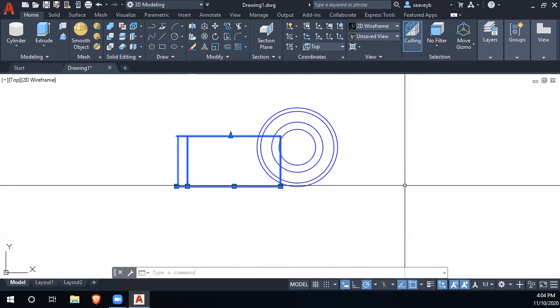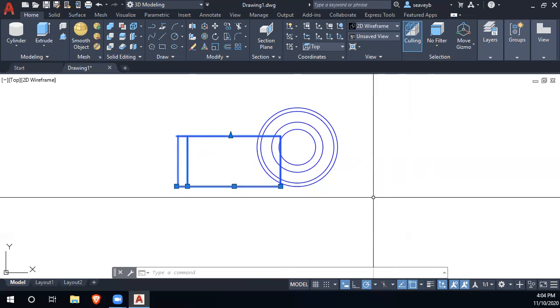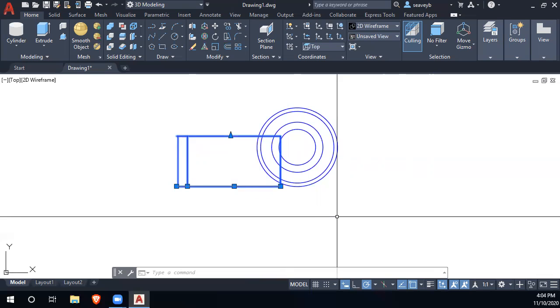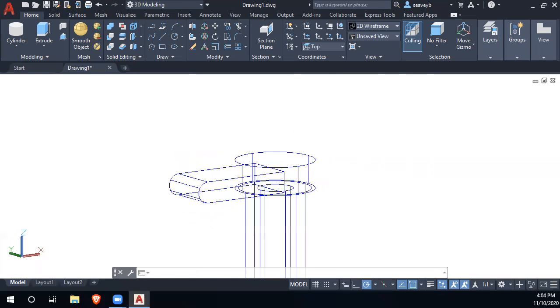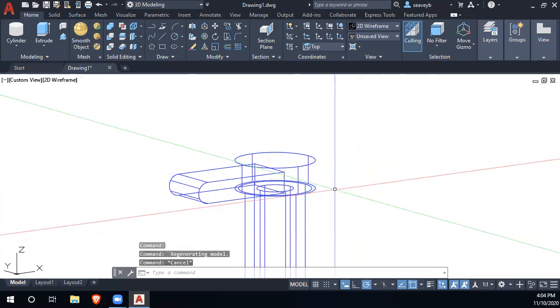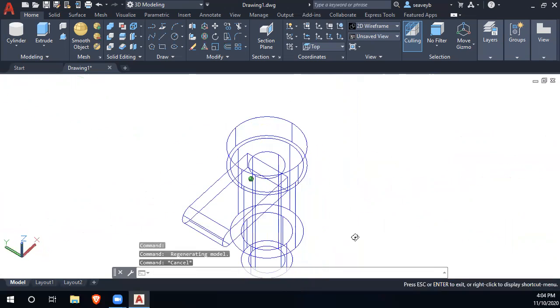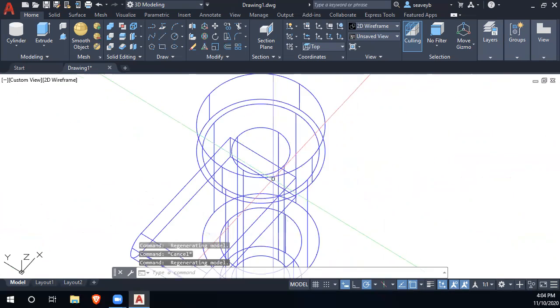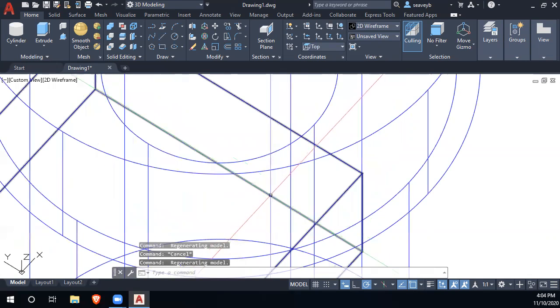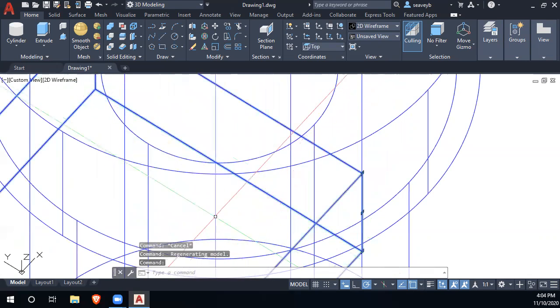I could use snapping. That's also quite useful. Let's see if we can make the snaps happen. I do need to put it into a 3D viewport here. So if I zoom in on this edge, so if I select this thing, I can snap to midpoints, right? So if I just use the move tool, let's see if I can make this work.